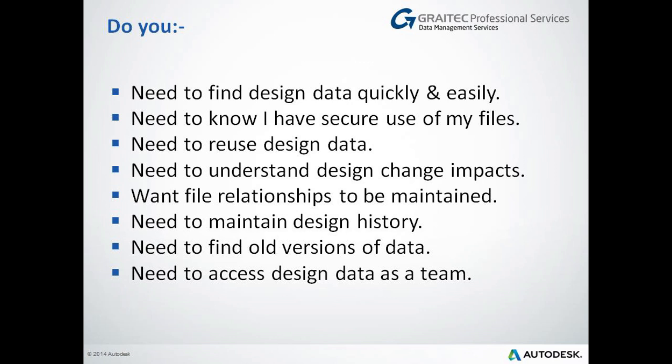with all the best will in the world, unless you have particularly good knowledge of the product ranges or the designs available, it's very difficult to understand the true impact of a change without involving a lot of people or a lot of background history and knowledge of that product. Another one is file relationships, particularly again with Inventor, where you have relationships between parts and assemblies and drawings. You need to maintain those. If you move a file around, relationships get broken, they need to be reassigned, reconnected.